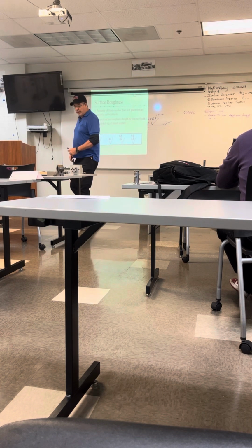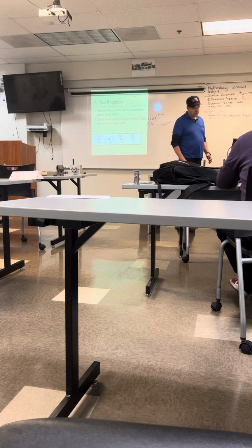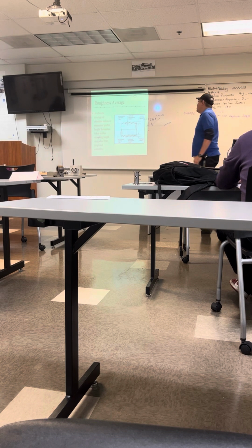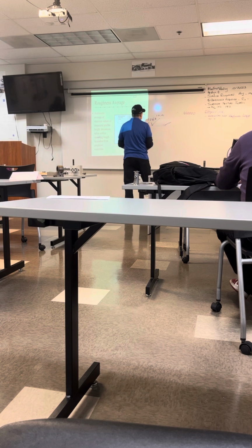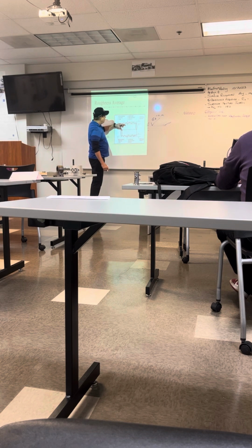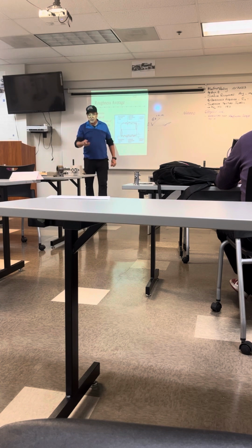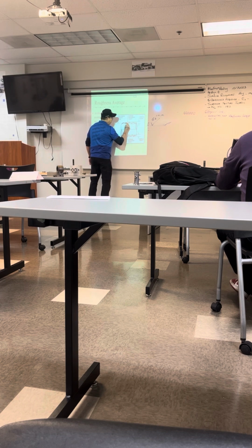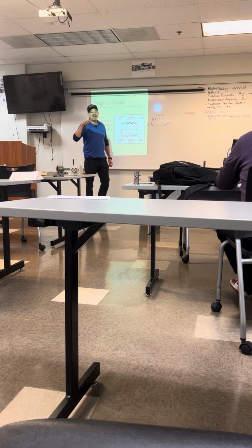If you go to the next page, guys, and look at your book right here, what are they talking about? For example, 63 millionths or 32 millionths. Well, it's the measurement of the irregularity looking through a powerful microscope. Any surface that you see, when you look through the microscope, will look like that. It's a combination of the shape of the tool bit, the feed, and how much the material is released from the part.